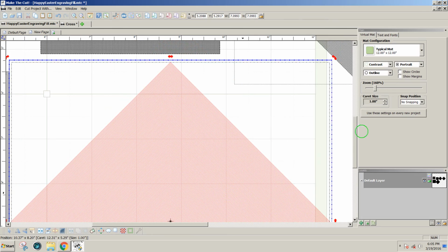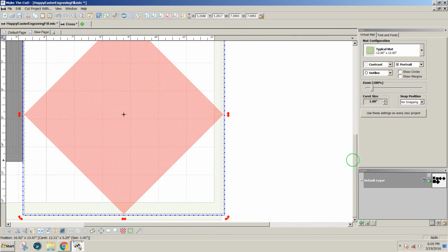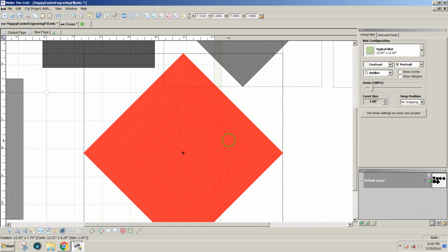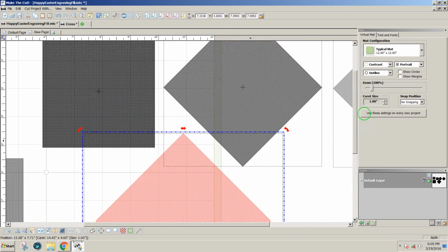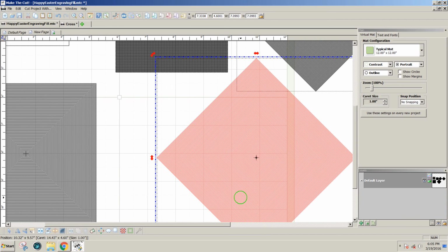Now it's important that whichever design you choose, all of the lines are joined in a single group, because we're going to use Boolean Join now with our desired pattern, and Boolean Join can only be used with two shapes. So let's say we want to use this island fill. I'm going to use Control C to copy, or you can go to Edit, Copy, and it'll be real slow because it's selecting every single one of those lines that we just made. As soon as it's copied, we'll be able to go back to our previous page and grab our design.